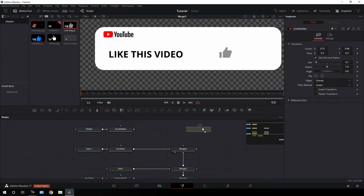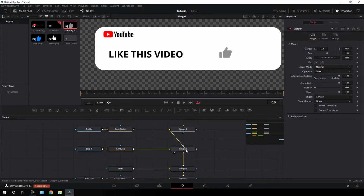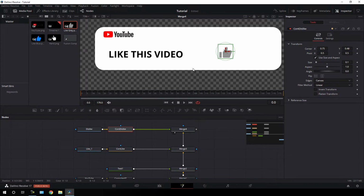So we have to take a new merge node and just drag this yellow point with this main output, green foreground point with this controller dislike, and just drag this merge 4 to the viewer and select this one, and let's drag it right over here maybe, and set this value something around 0.9, and let's rotate this button. So I'm going to set this angle value 180 degrees and just drag it down a bit. All right, it's perfect. And then we have to create an animated like from gray to blue.